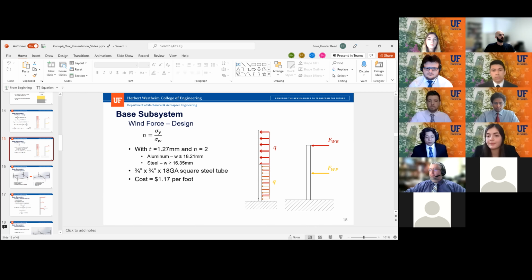Okay, so you have no safe position for the max winds. You're assuming that it can take the winds directly on at 90 miles an hour. Our safe position would be flat to minimize the effects. We use this as a worst case scenario, if something hit it and rotated it, like an up gust of wind or something that would rotate it. We wanted to design it to essentially take no damage.